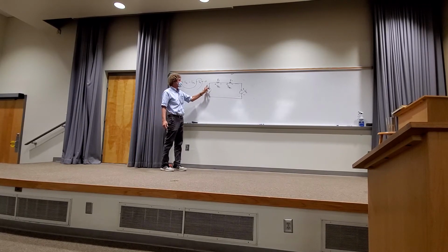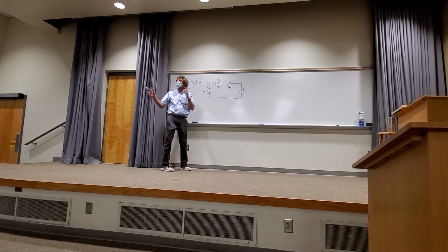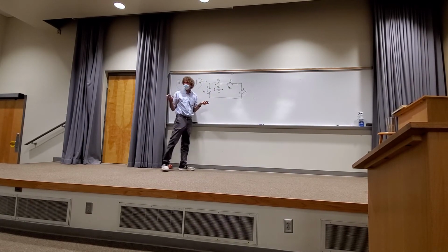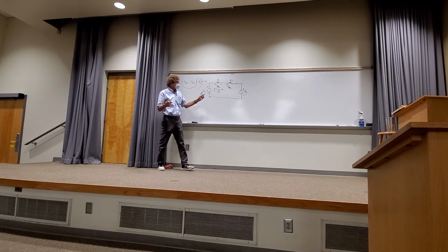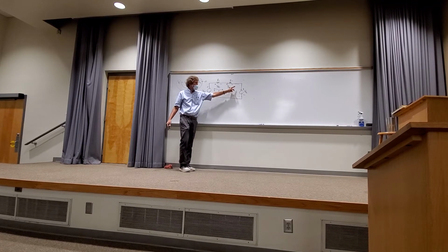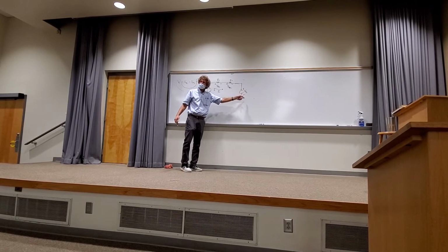So that's an increase of V1, then a decrease because I went from the plus to the minus. Now the only reason I would sign that way, I'm assuming the current will flow this way. And if it's wrong, the current will be negative. So there's going to be a decrease and then a decrease, two negatives, right? Now this one's another negative because I went from the plus to the minus. If they were reversed, it was minus plus, it would be added.